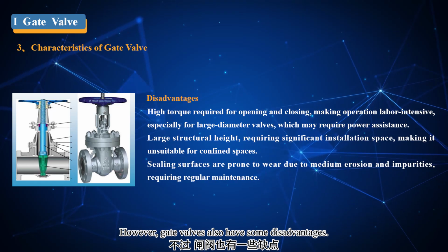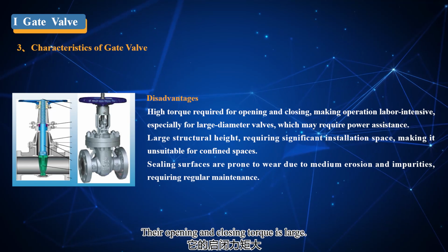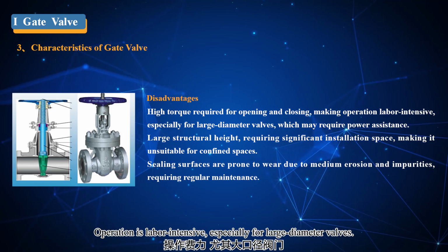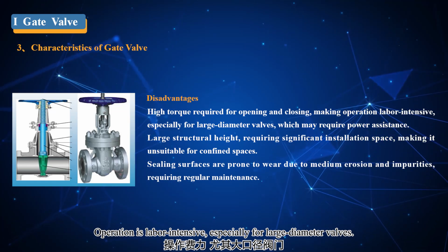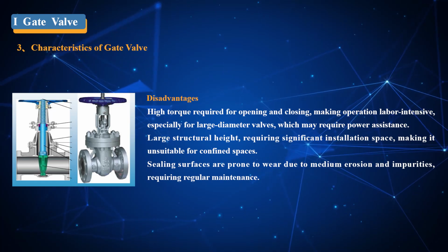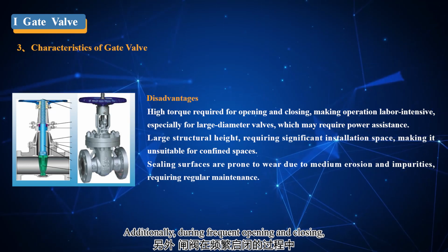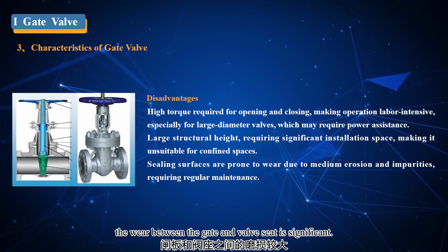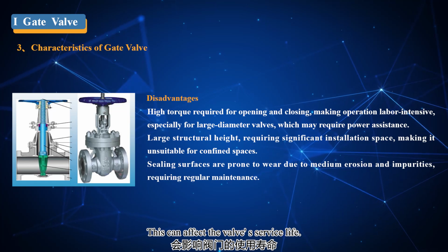However, gate valves also have some disadvantages. Their opening and closing torque is large. Operation is labor-intensive, especially for large diameter valves. They require power assistance. Additionally, during frequent opening and closing, the wear between the gate and valve seat is significant. This can affect the valve's service life.